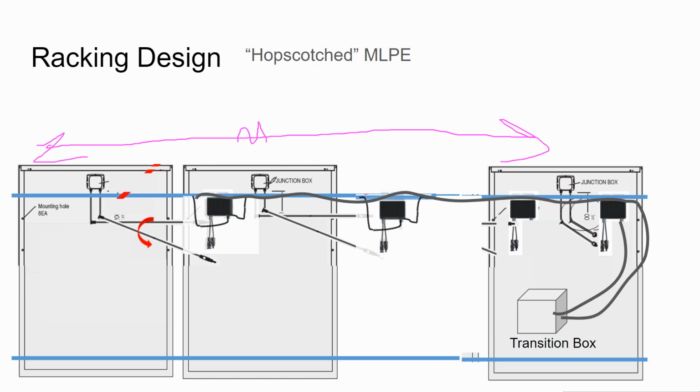There used to be a blind spot in inverter ground fault protections for multi-circuit arrays. And so when the conduit would pull apart, it would bite into the wire, and then the wire would start ground faulting. And if all the planets aligned correctly, the building would burn down. Now there's a limit of about, I think it's 120 feet, where you have to put in an expansion joint.